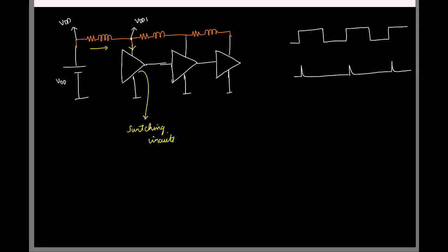It is essentially the drop across the resistor, which could be small, but the main issue is the drop across the inductor. What is the voltage across an inductor in terms of its current? It is the derivative of the current. So this is a spiky current, and the derivative of it is going to be huge. So the voltage here is going to see huge jumps, and the same will propagate to the later stages also.